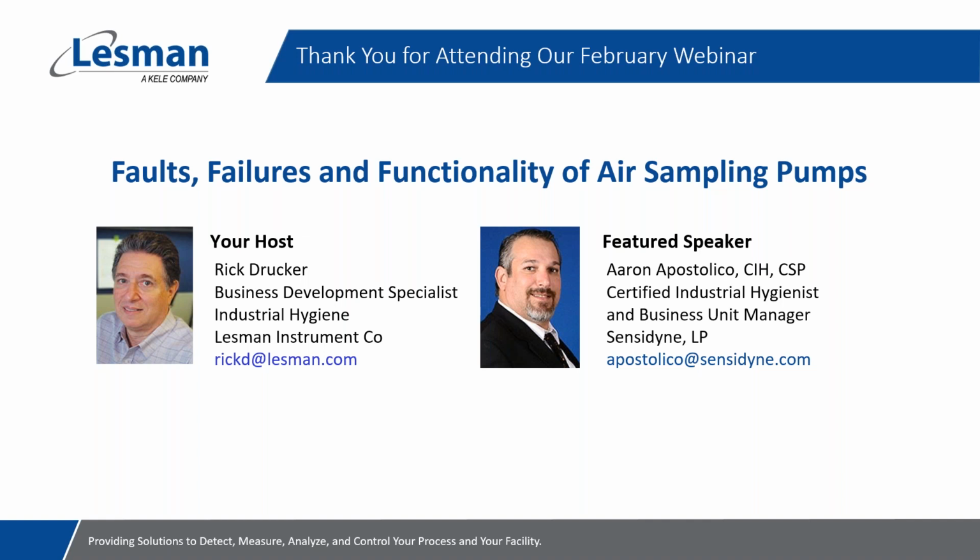So if you have a fully charged battery and you are nearing your thresholds, you're probably not going to get an 8-hour sample. You might want to look at getting a pump that has higher threshold capabilities, so you can make sure that you get your full 8-hour shift. You might also consider bringing a second pump out with me, so that if it does fault because of that battery, I'm able to calibrate another pump and have that connected to the same media, so I can now complete my sampling event for the day.